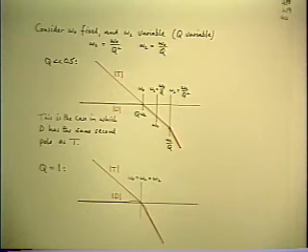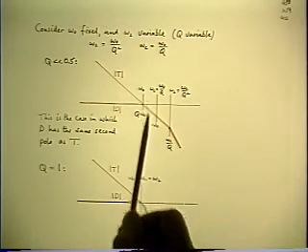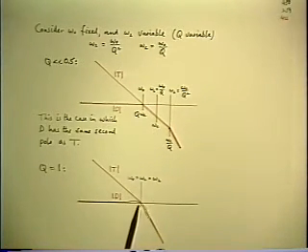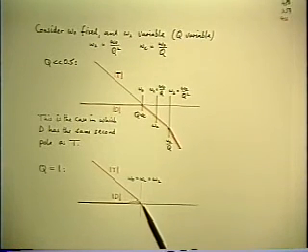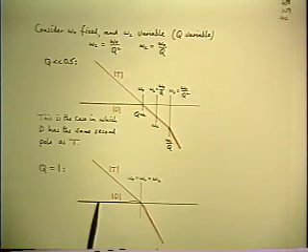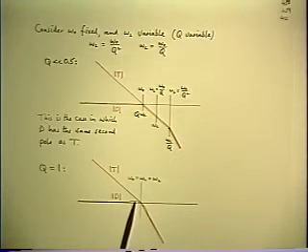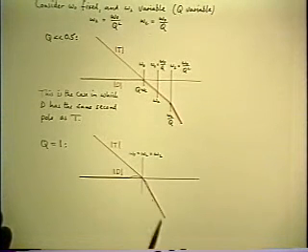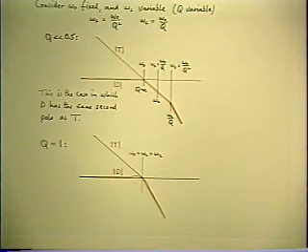Now the next interesting case is, what if Q is 1? Q is 1 if the omega 2 comes back down to be equal to omega 0. So the second pole in T is at the original crossover frequency. So the shape of the quadratic with a Q of 1 means that D is 0 dB and goes through unity at the corner frequency and bulges up a little bit below it, and then bulges up above the other asymptote and falls off at a double slope.